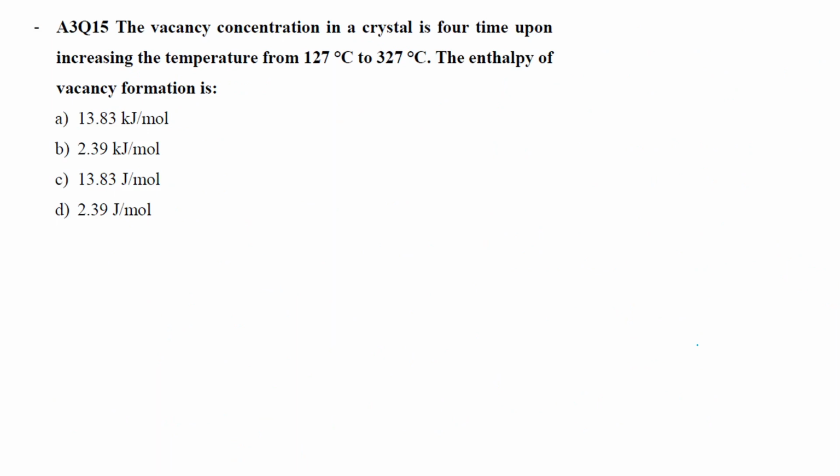All of you solve the next problem. It's also a similar kind. The vacancy concentration in a crystal is 4 times upon increasing the temperature from 127 degrees Celsius to 327 degrees Celsius. The enthalpy of vacancy formation is, the options are given.